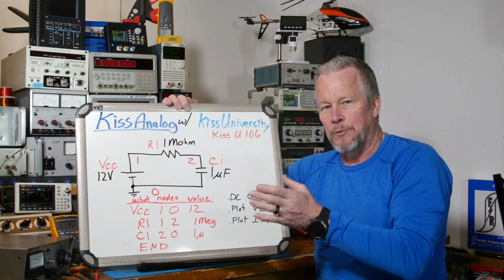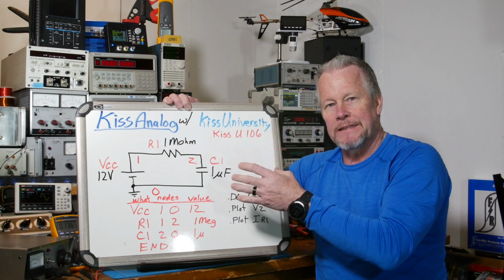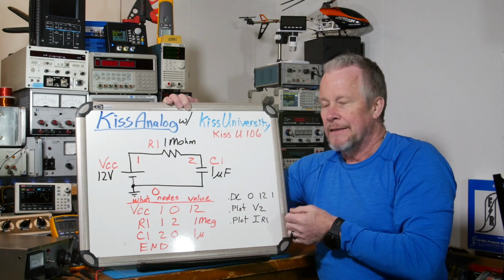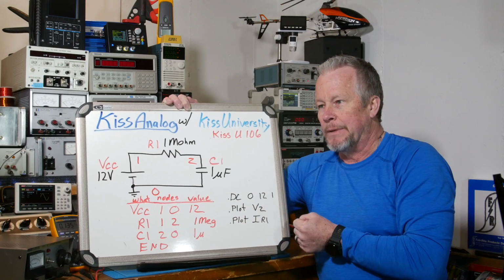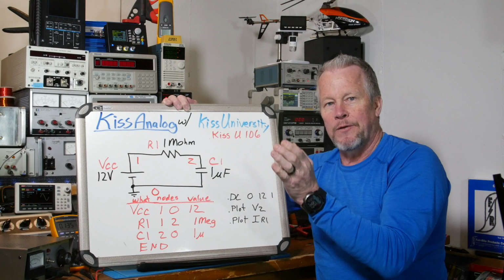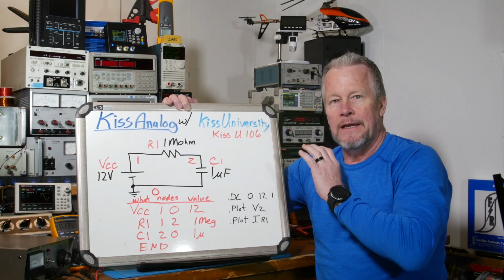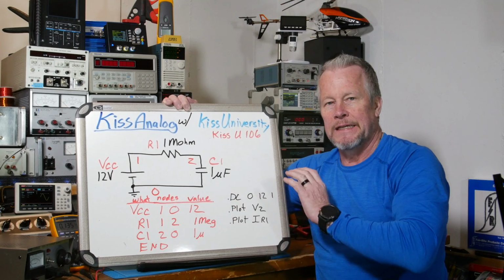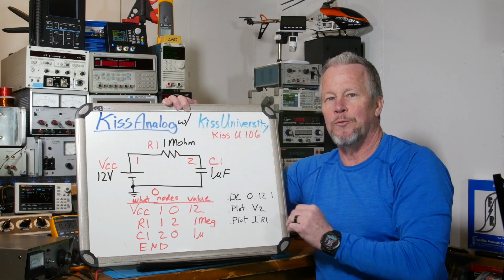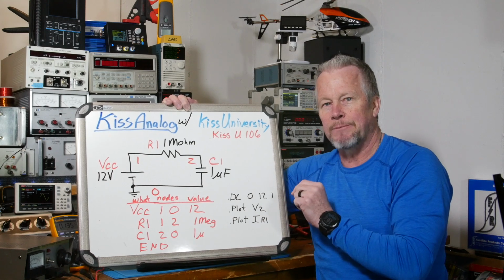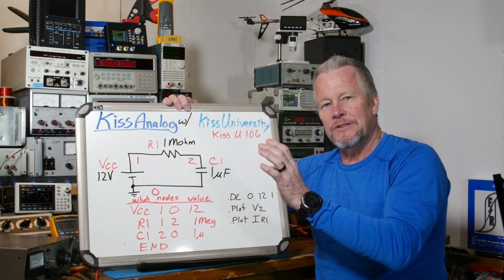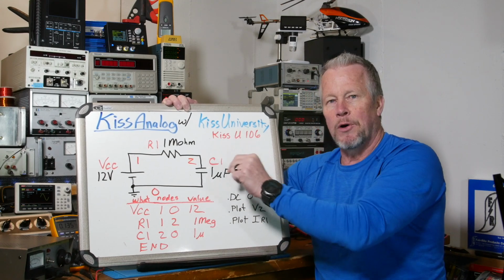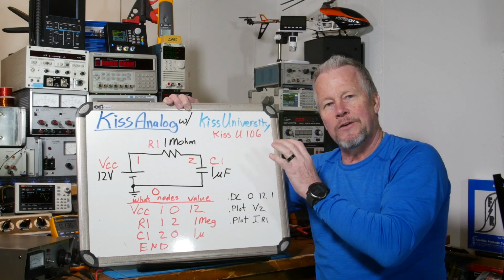That's why in MicroCap what we'll see is there are 2 different transient analyses. One is for the probing and one is for the pre-setup. The pre-setup has advantages because you can set up different graphs with different XY axes, and you can have all that set up for you so that when you run your analysis, it plots it the way you want it to be. And then when you change something, you can get a new plot and change it the way you want it to look.